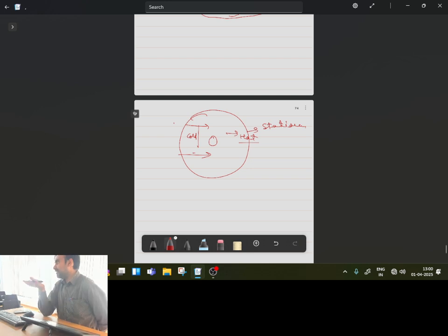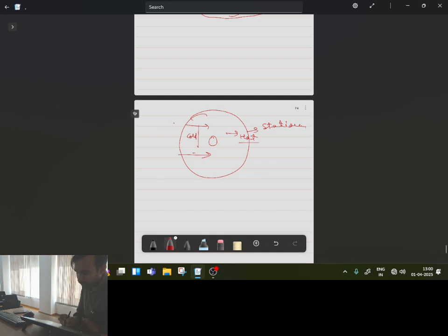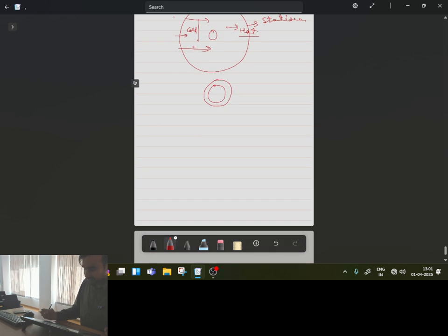But whenever you introduce flow, the flow tries to channelize the transport of the property in a certain direction. There is a competition between flow and diffusion, and which rate is more controlling matters. If flow is happening at a very low rate, there will be deviation from the circle, but the deviation will be very small. However, if flow is predominant, then the temperature profile will be more elliptic. Is this point clear? All are understanding this point?